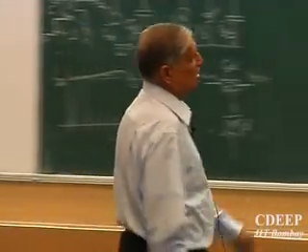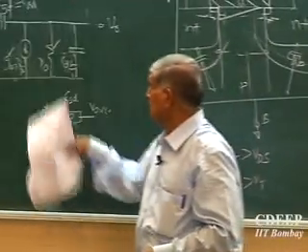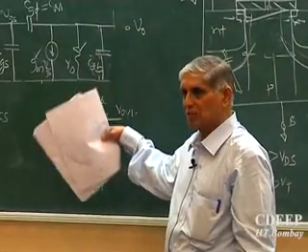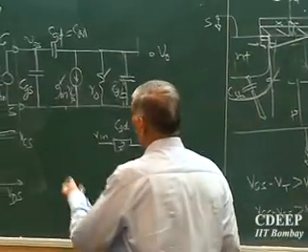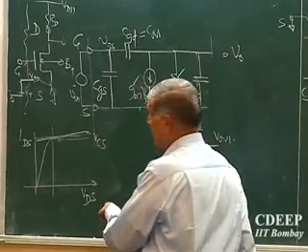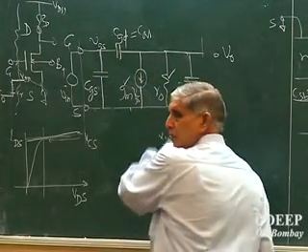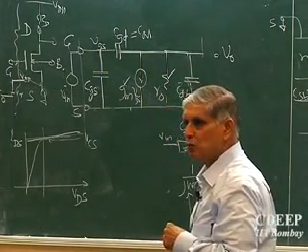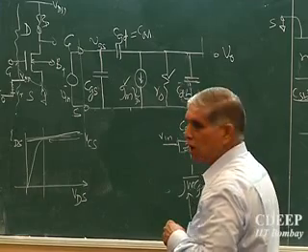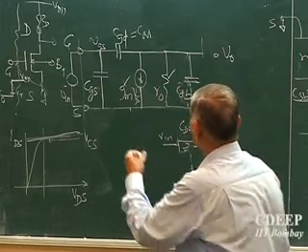So now we see this is the equivalent circuit of a transistor under all frequencies. Okay. If I say low frequency circuit, then what should I remove? All capacitances can be removed from here, and once I remove all these capacitances, the circuit is just simple.